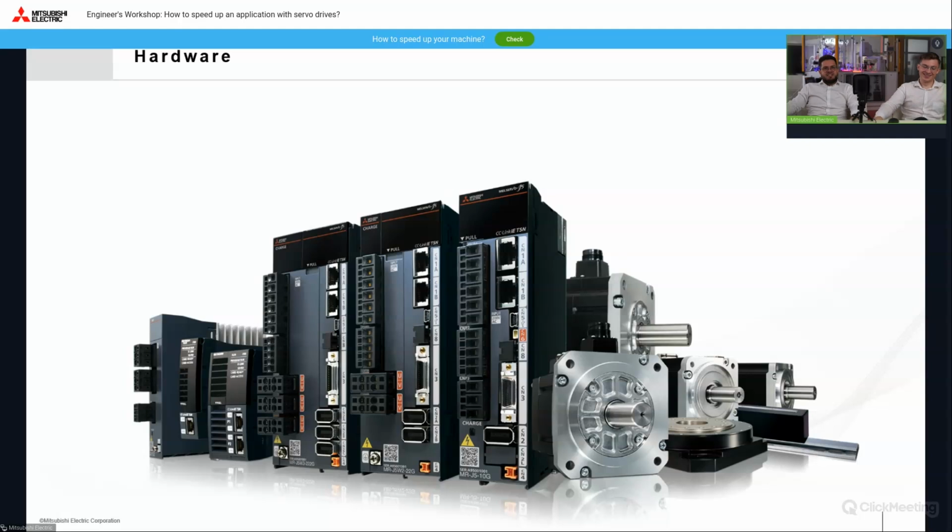Not really. Acceleration is more important in the context of servo applications, which are mostly start-stop. If the maximum torque of the motor doesn't allow achieving a higher acceleration value, we can use the torque increase function.